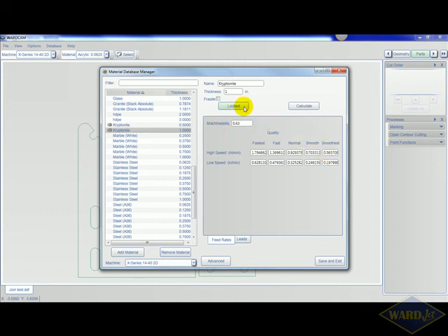So you can, of course, if you want, just manually type in numbers. The drawback of doing that is that if it's not based off the machinability, then when you go to make a copy of the material, it's not going to do the calculation properly. So try to use that machinability number if you can.